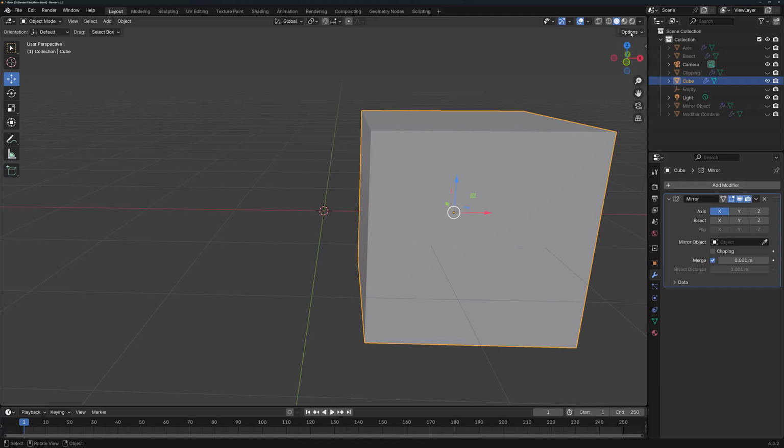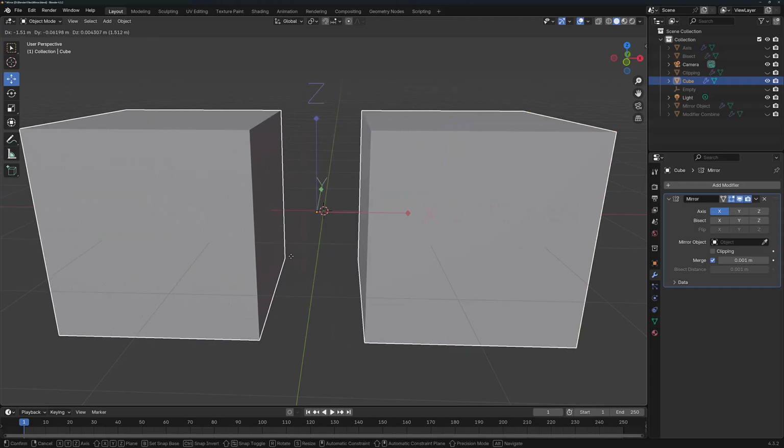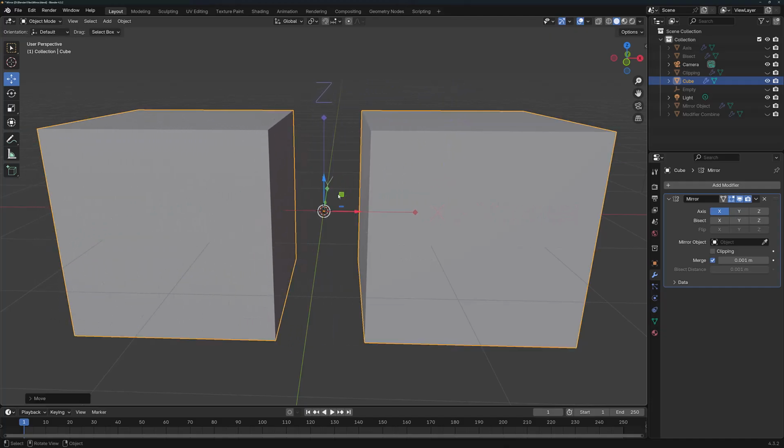However, if you were to move your object origin, for example, say press the G key, you would be able to change the object origin's position, and therefore the geometry would begin to mirror along the other side of that specific axis.